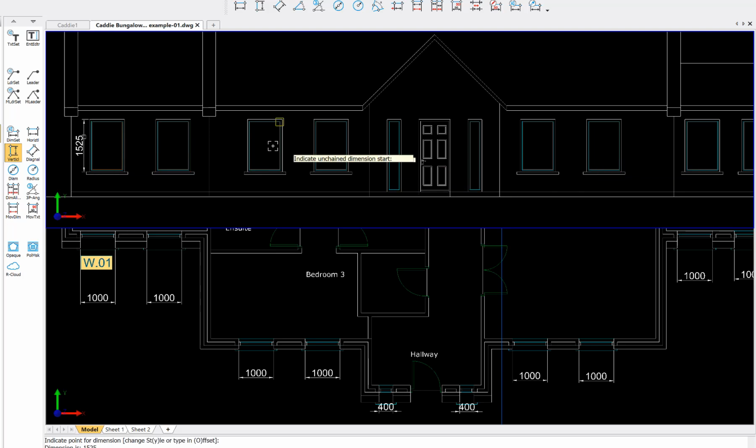And these are all the same, so we could do them all, but suffice to show that here we have our full height to 100 windows, and then we're back to here. So the dimensioning tool is automatically picking up the endpoints there. So we've identified the sizes of our windows.